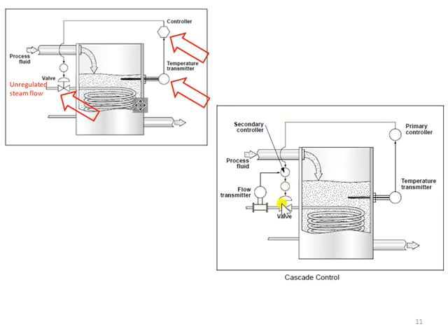The rest of the effort to regulate the flow rate will be on the secondary controller's objective. So the performance of the temperature control will be better since the steam flow rate has been well regulated by the secondary controller.